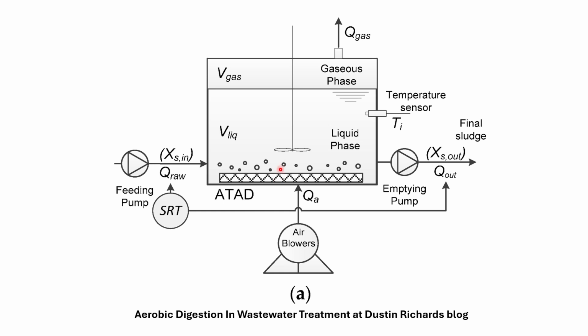As it's aerated, the sludge is going to start falling out. The liquid, or supernatant, is going to come up and we're going to be able to take that off, and the thicker sludge with higher concentrations is going to be pumped from the bottom. Very slow process. Again, slow in, bubbling, mixing, moving, takes a couple of days.